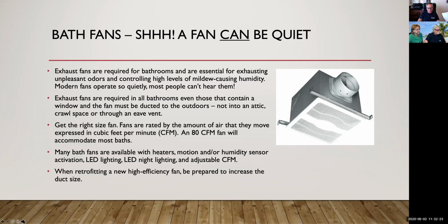Cabinet materials are very important. Plywood can be veneered on one or both sides with either wood, melamine, or plastic laminate. And if you look in this picture, you'll see that the plywood has a beautiful birch veneer, which is very smooth and free of knots and cuts. But plywood is also lighter and stronger than medium density fiberboard. Wood veneered interiors can be painted or stained. That's a real plus, but they are more expensive than MDF.